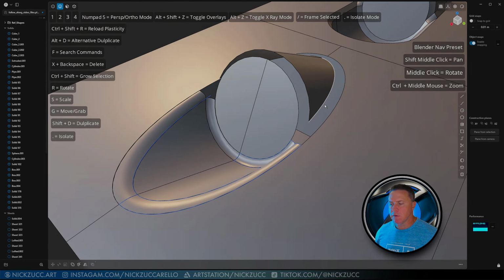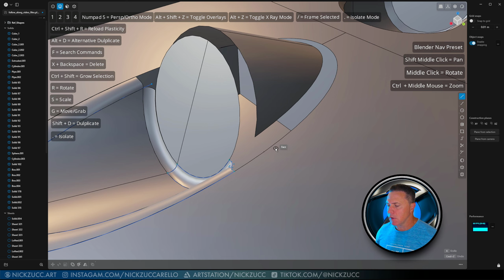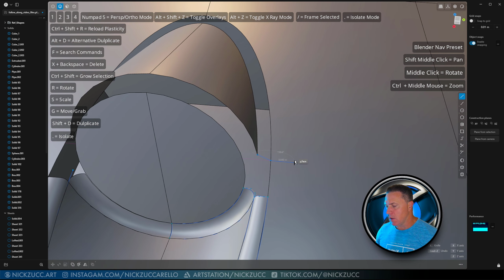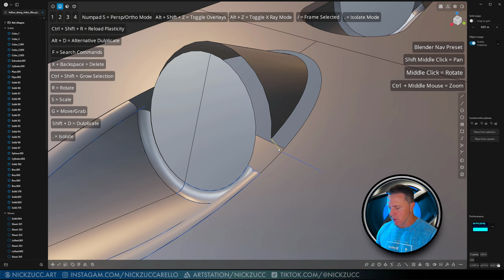Okay. So we're going to continue to work our way around the model, and I'm going to use the line tool here. Again, just clicking on a point like this and seeing where I can find along this edge, and it says this closest edge face. Go ahead and click that. And then if I want to right click it in that, I can just hit Shift A, and that'll bring up the line tool again. I'm just going to click and then drag out along this purple line like that, just to get a line that we can connect to.